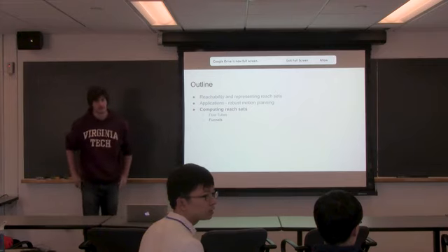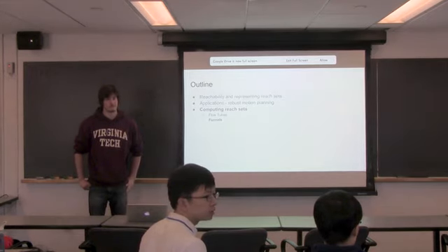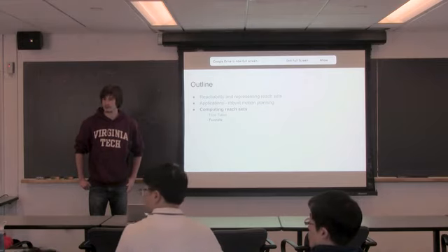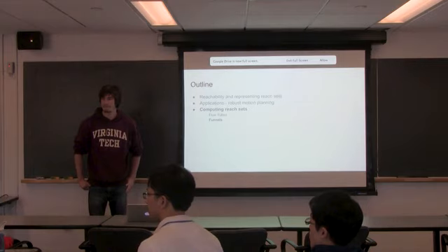The polytopes generally require linearization of the system, and there's a limit to the validity of the range of the linearization, and that's one of the things that limits the size of the polytopes. But it is kind of the standard thing that you do for nonlinear systems, right? Which is you're making them piecewise linear, linearizing them at every step. And there's other techniques that people have developed with flow tubes where you do require the input system to be linear. Right here it can be nonlinear, but it's an approximation.